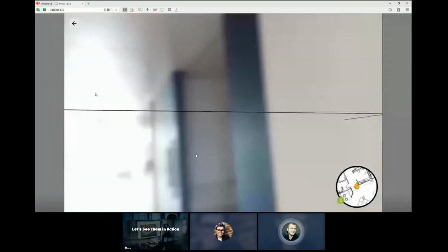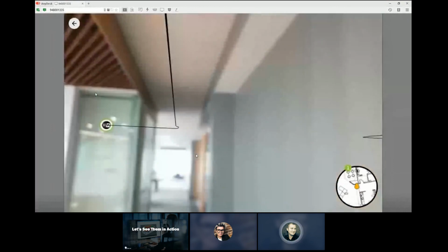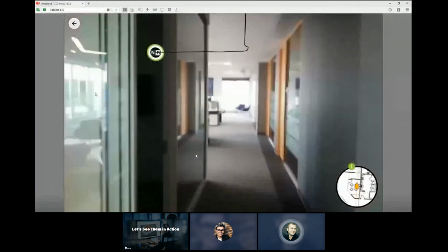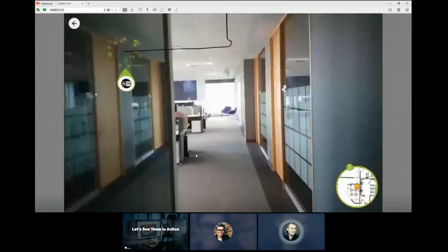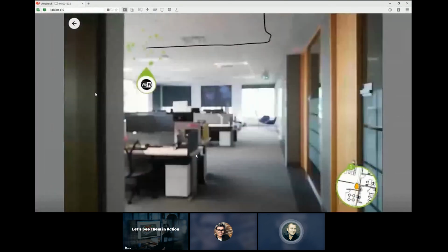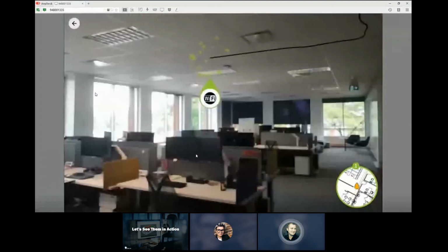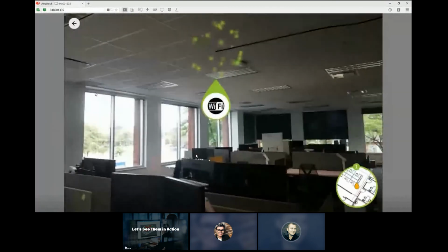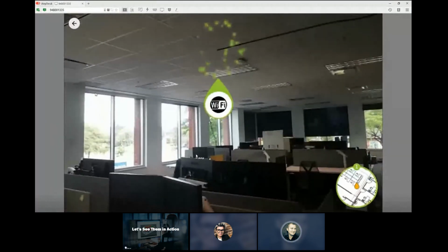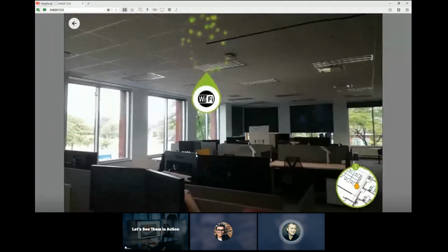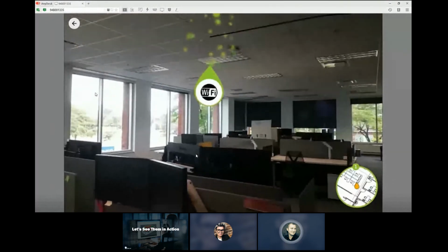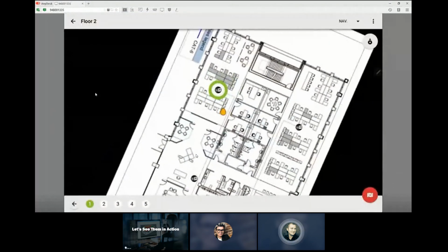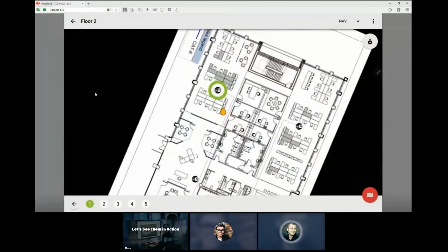It may give you the impression that the height is not correct, but technically it should be inside the ceiling. Then I follow. You see the little map on the bottom right corner, and it shows you where you are. And then you see that the AP was supposed to be installed here, but it was installed maybe 1 meter, a few feet, away. And so you could actually validate the installation and find where they are, and if they are installed as designed or not.